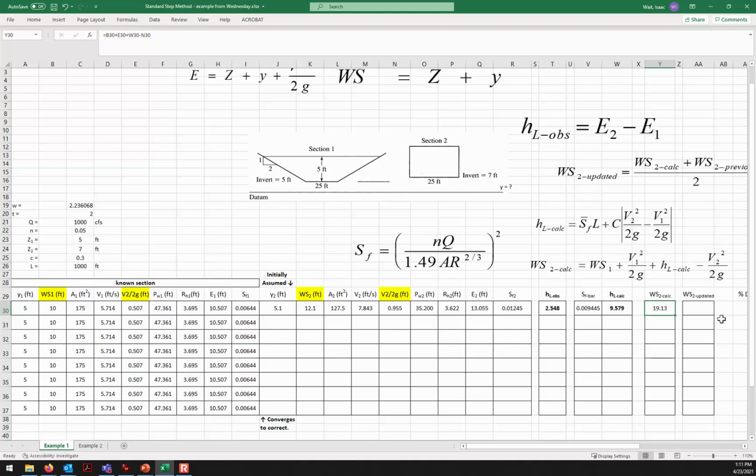When we were doing this example on Wednesday, I think I had accidentally referred to the V instead of the velocity head. I was getting some number around 24, and I was a little bit confused. Luckily, we ran out of time, so I was saved by the bell on that one. But later on, I figured out what the issue was. In my formula, see how this reference is going to the velocity head at 1. I accidentally had my equation referring to V1, and it's not V1, it's the velocity head at 1 in this equation.